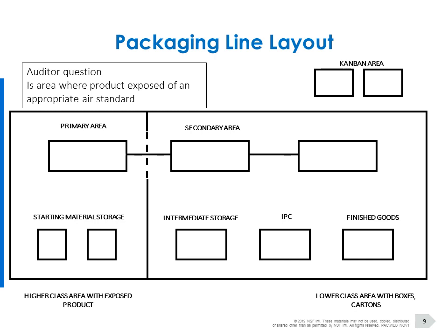This diagram shows a schematic of a packaging line, and particularly if a packaging line is taking bulk products such as oral solid dose tablets or capsules or perhaps granules, then you will typically see a primary area whereby the product is actually exposed and is then contained within its primary pack, and then going through into the secondary packaging area where you might have leafleting, labelling and cartoning.